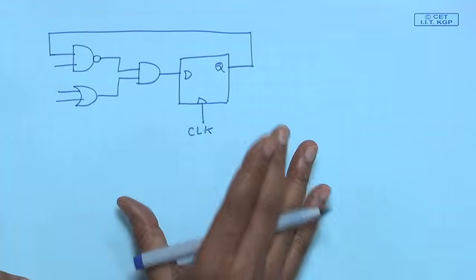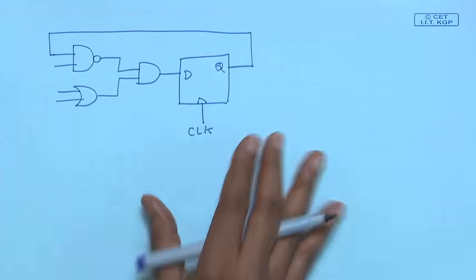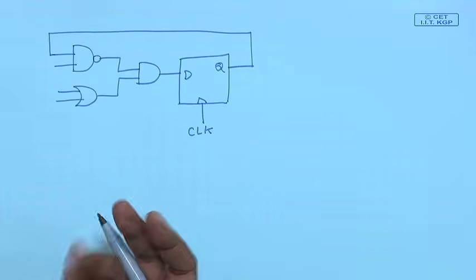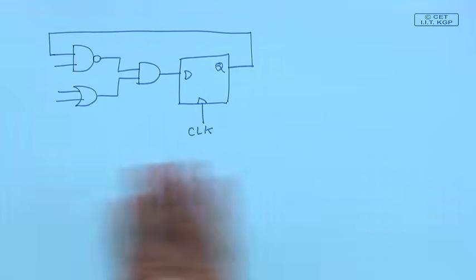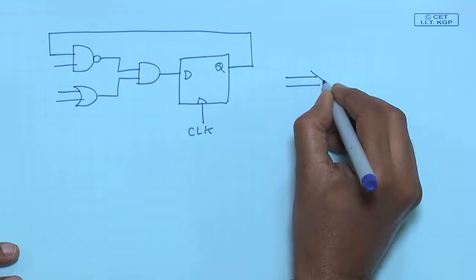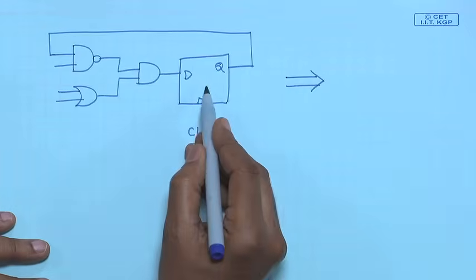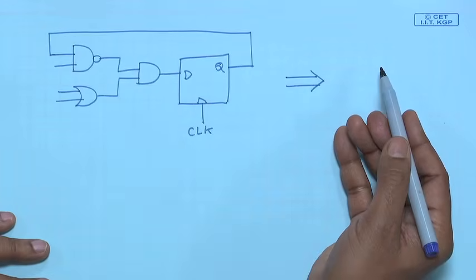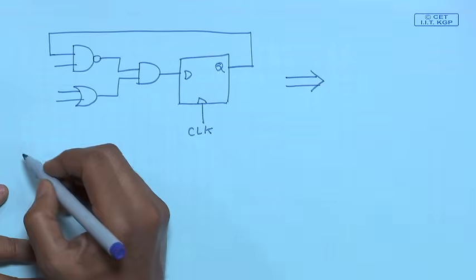So, each of the register level components like your registers, multiplexers, then adders, they will get translated into a gate level design like this. And finally, from this gate level design, each of these gates and flip flops can be translated into equivalent transistor representation.